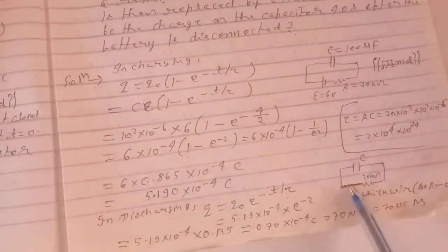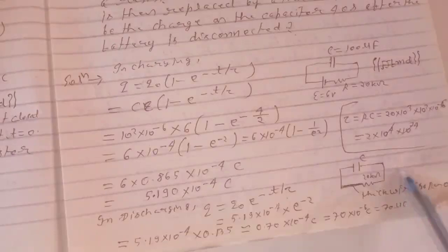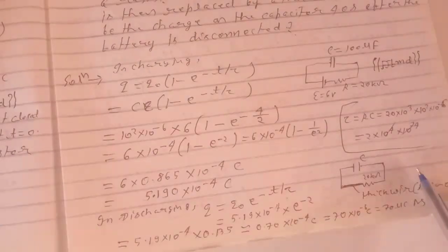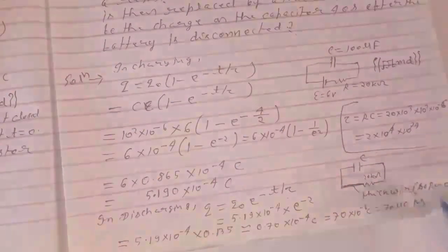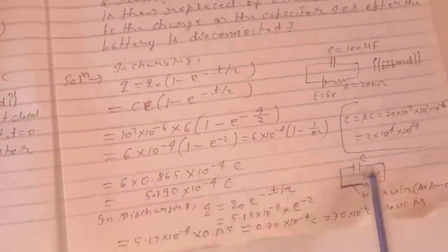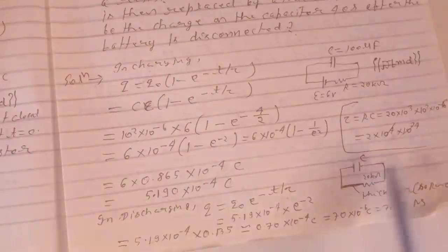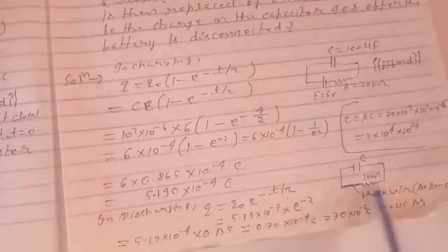And it is also a thick wire, and we know that R equals rho L by A. So the area is more, the resistance will be less, so its resistance is very small compared to this, so it is considered 0. So we will only consider that the capacitor is discharging through this resistance.